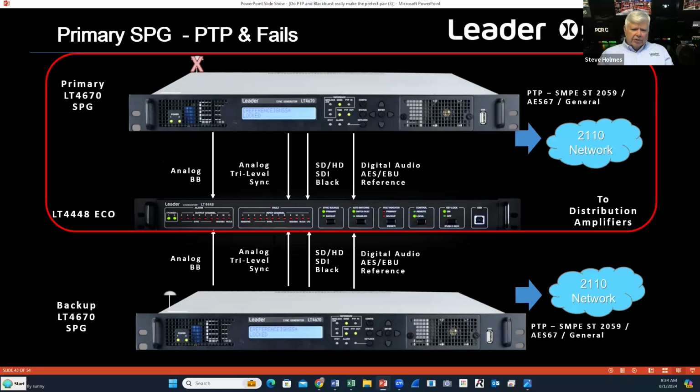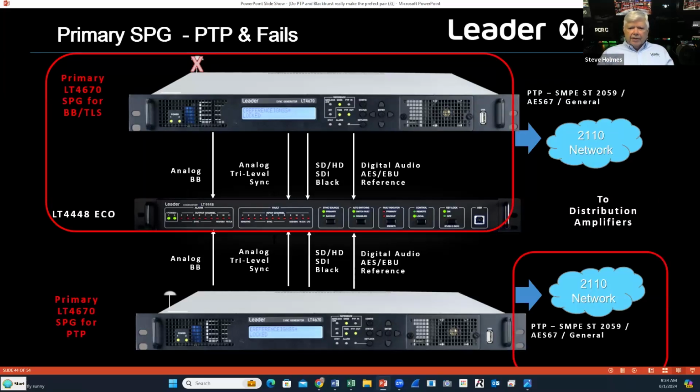The bottom generator is still locked to GPS, so it's a better, what they would call, clock class, because it is GPS locked versus sitting on the internal crystal. And it will, via the BMCA, best master clock algorithm, PTP will walk to that second generator, which is good.